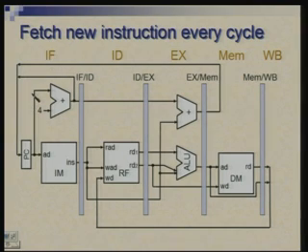So, that is very important, and the complication here is that since there are many instructions in the pipeline, there will be some instruction here and there will be another different instruction in this stage or in this stage. Okay. So, we are trying to mix up things, but at the moment let us ignore that. We will come to understand the implications of that, but right now our focus is on quickly calculating PC plus 4, and for the moment let us imagine that we do not have BEQ.